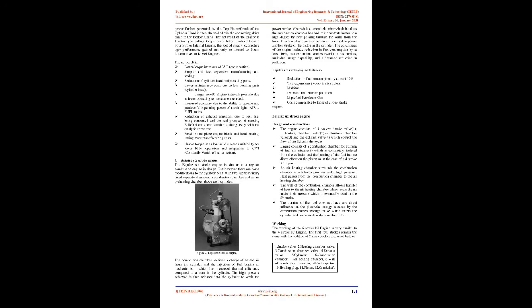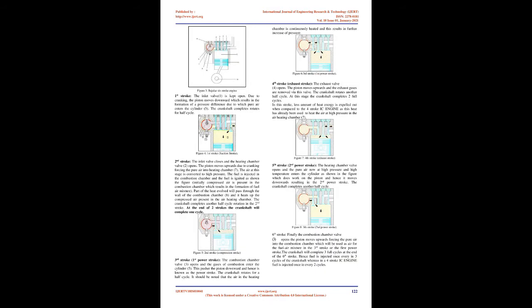1. Crower 6-stroke engine. In a 6-stroke engine patented in the US by Bruce Crower, after the exhaust stroke, fresh water is injected into the cylinder and is quickly turned to superheated steam, which causes the water to expand to 1,600 times its volume and forces the piston down for an additional stroke. This design also claims to reduce fuel consumption by 40%. Crower's 6-stroke engine features.